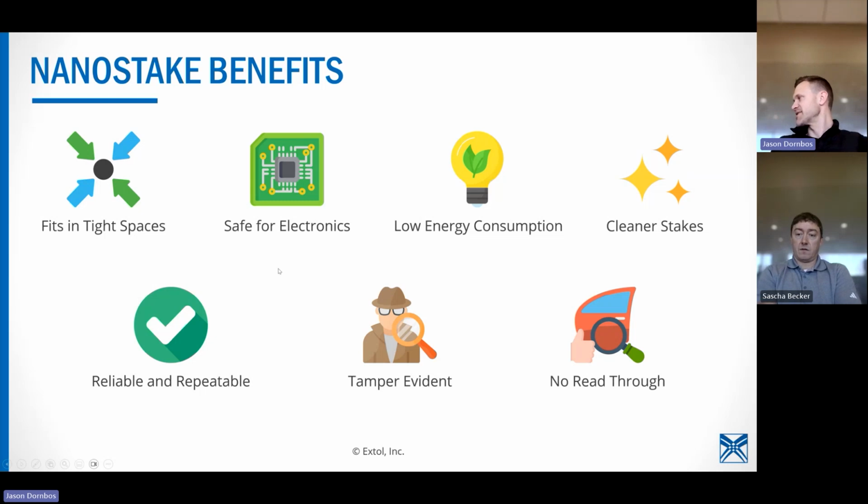Have we come across a material that doesn't work with InfraStake? It all kind of depends on your cycle time expectation. Yeah, some take longer than others. Higher melt temperatures. Some of the more challenging ones would be a clear part, which can be staked, but a clear part with a really high melt temperature and glass in it, like all these things that are trying to prevent the part from melting. We have to overcome all of that with whatever staking technology.